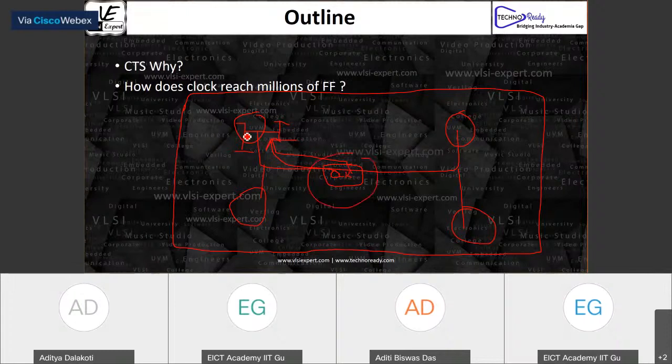I'm saying to every node, I'll create a symmetric wire distribution so that RC to every flip-flop is the same. But we are meeting the timing spec, right? The timing spec with respect to the clock is that you make the clock have minimum skew so that your other things are well synchronized. Why do we need to put any buffers in between? Is my question, I guess. So let's see.